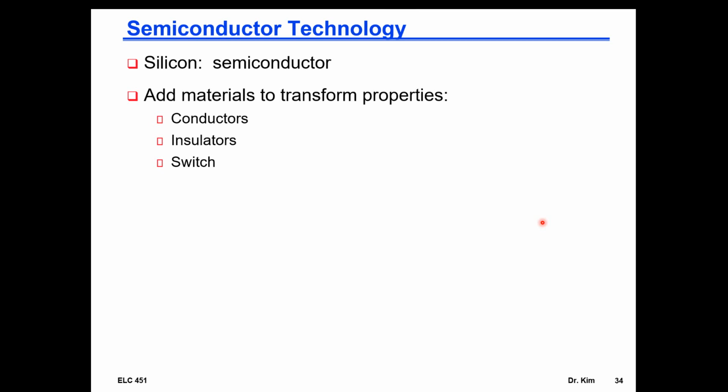scale. What makes it challenging is actually the trend of having more devices and making the devices smaller. That makes it challenging because the process is a lithographic process. As the geometries get smaller, you cannot even use regular optics for visible light anymore. You have to use ultraviolet, and that's not even enough. Ultraviolet is too big of a wavelength for the sizes and geometries that we're talking about. So you have to use phase shift lithography based on ultraviolet that relies on the differential sizes of the wavelength. So it's very complex.